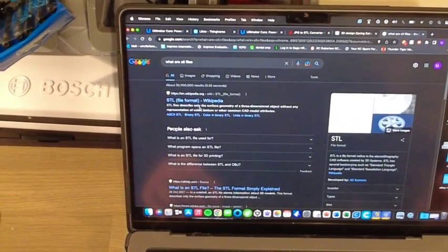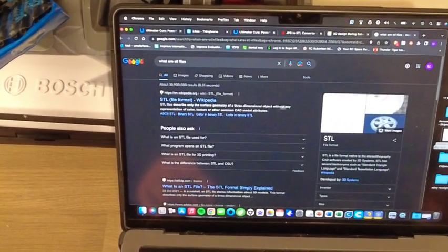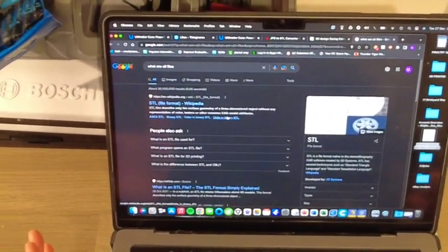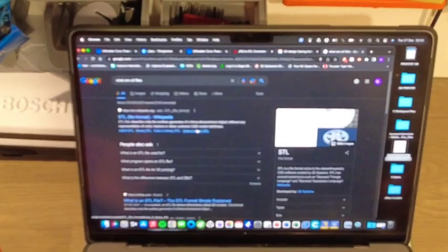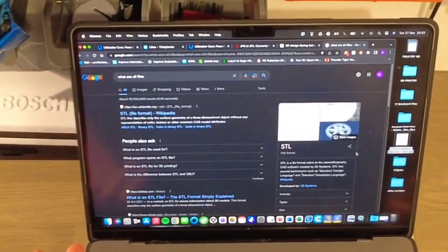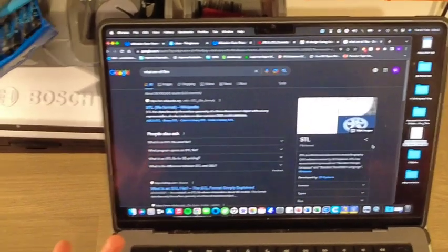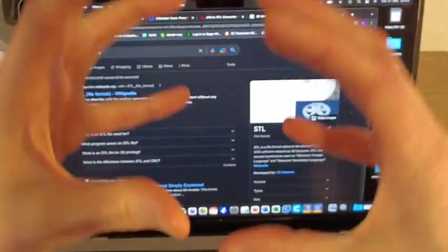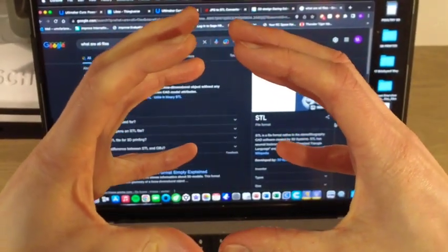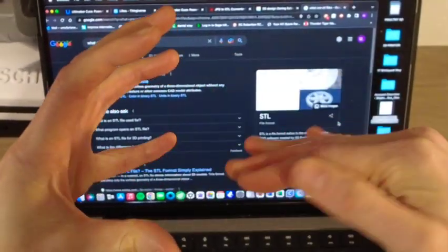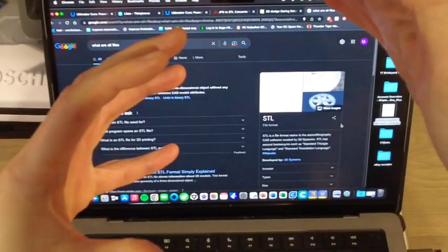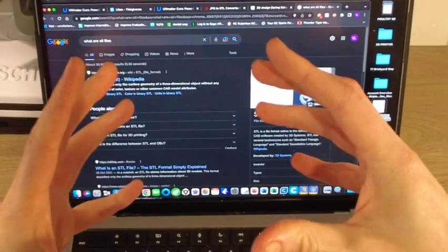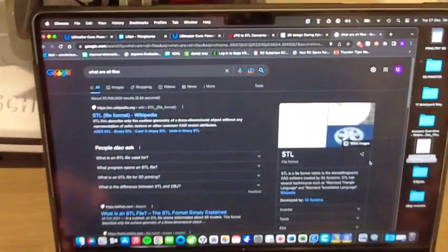So, STL files describe only the surface geometry of a three-dimensional object without any representation of color, texture, or other common CAD model attributes. So basically, the STL file is like a 3D object that you can put into a slicer, and what slicers do is take that 3D object, and you imagine that the extruder has to do each layer individually, so a slicer cuts it into several layers and therefore translates that 3D object into a print that the printer can cope with. So that's what a slicer does in essence.